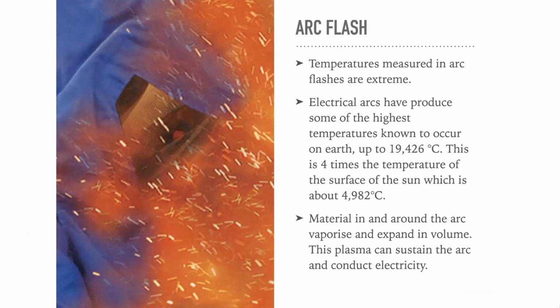It's still an area that's not well supported in terms of recycling of non-lead batteries. Lead acid batteries are extremely easy to recycle because they actually have a positive cost at end of life. The lead is still valuable, so someone will pay you for them. Battery systems that are not lead have a cost to recycle. There are some limited options, but there are companies rising to the challenge, everything from just crushing them, turning them to road base, to actually separating out the materials into its constituents and then repurposing those. So I can't give you a definitive answer, but it really would fall under local regs and what the recycling requirements are for batteries.